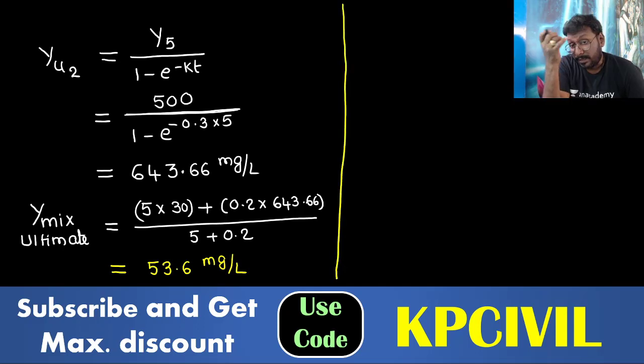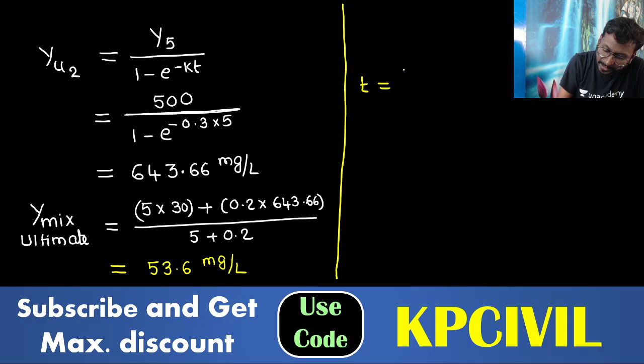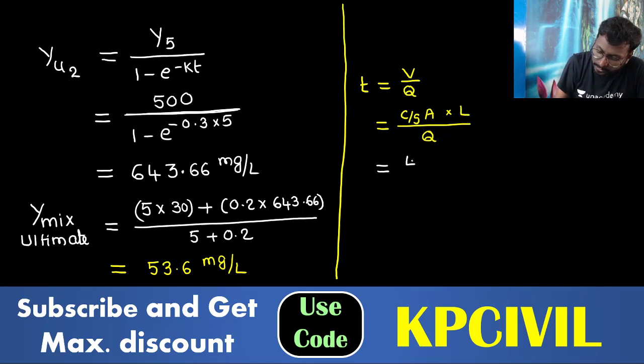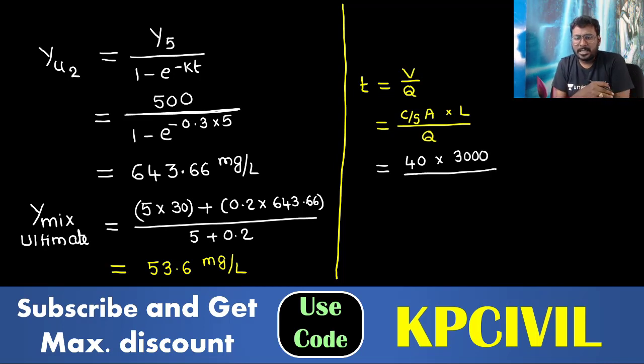Now, to estimate the remaining, first time is important. Time is equal to volume by discharge. I told you already. Volume is the cross-sectional area of the river into the downstream length, by discharge. Cross-sectional area of the river, how much? 40 meter square. Downstream length 3 kilometer. So 40 meter square into 3 kilometer, 3000 meter. What is the discharge? Will you take 5? No.